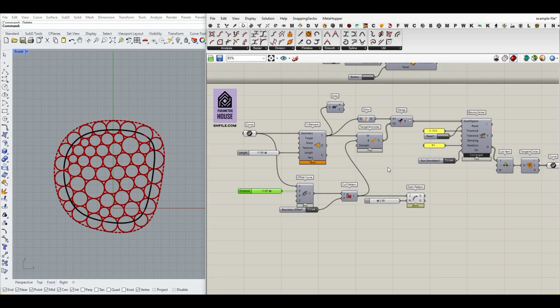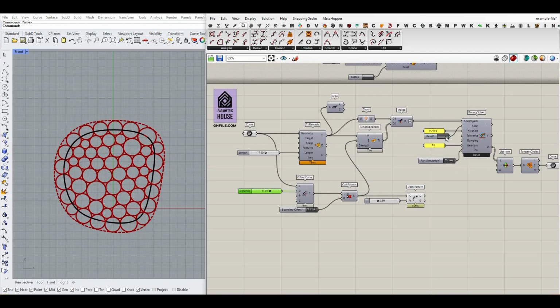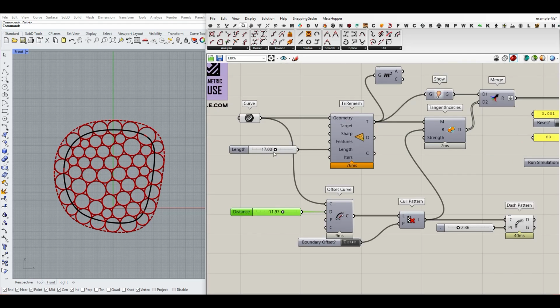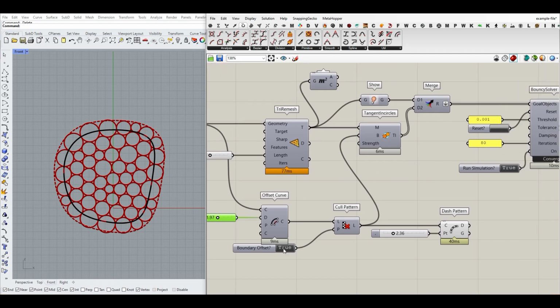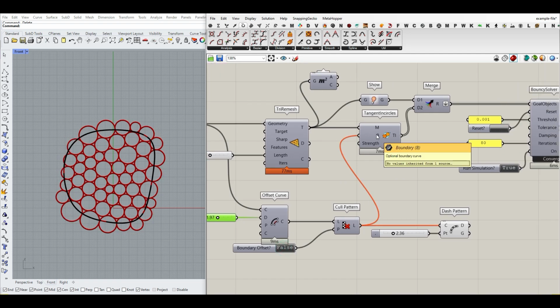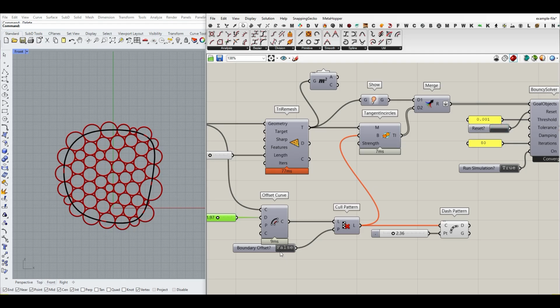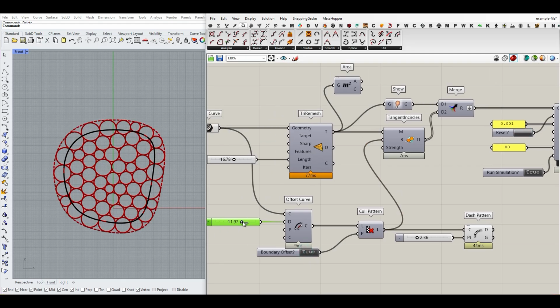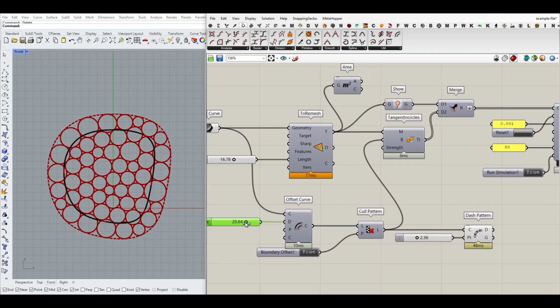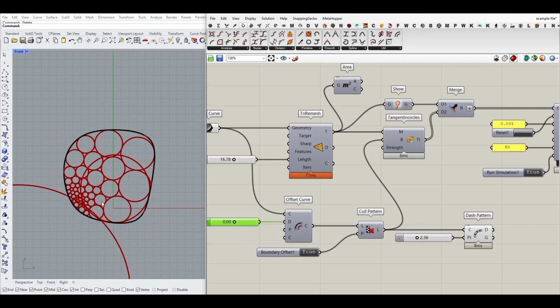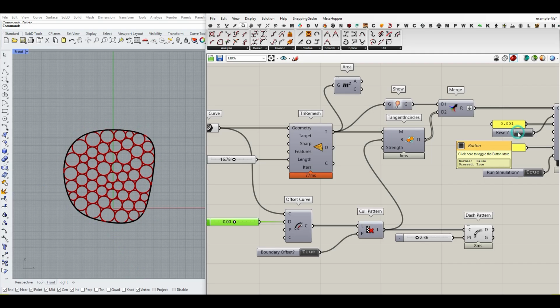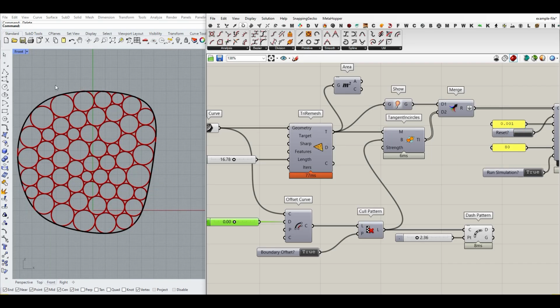But remember, whenever you use that, if you run the simulation, sometimes it's going to have problems. So remember, if you want to solve it, it's easy. Just turn off the boundary offset without any boundary, run the simulation, and then give it a boundary so it expands. And then what you can do here is just scale it to 0. And as you can see, it's jumping here and it will have some problems. Then reset the simulation and you can see it's on the boundary.